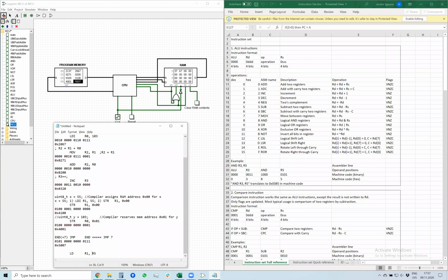So there would probably be an at symbol in front of it. I think this is how ARM Cortex microcontroller assembly language says it. Basically, it says load into register R1 the value that is stored in RAM address pointed to by register R5. Our processor could have this functionality, but it would add so many new cables that we didn't want to do it. But generally, yes, you can store a pointer into a register.